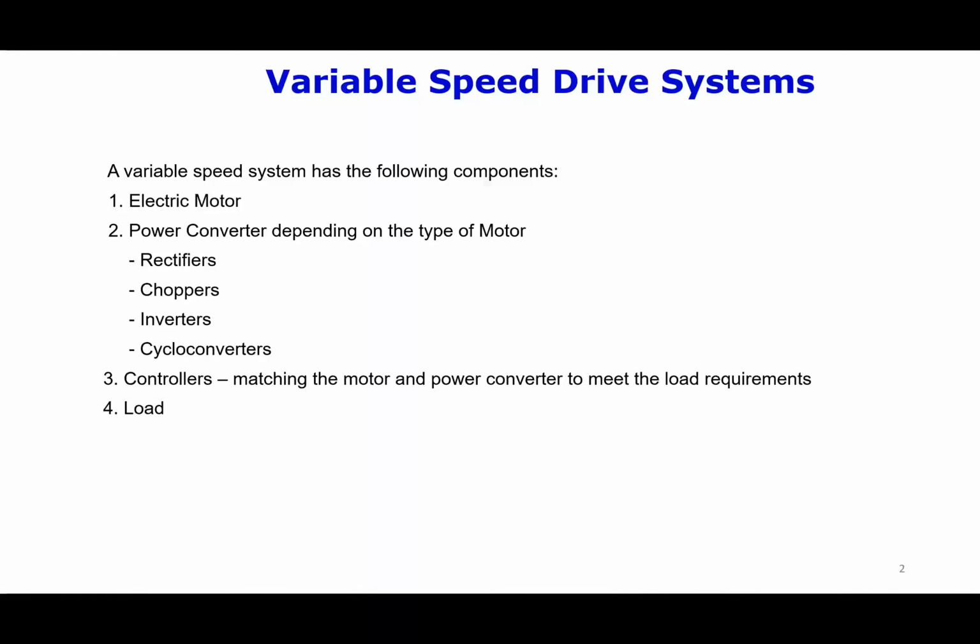Understanding of the power electronics and power converters is very important because power electronics is the enabling technology for the control of motors and to achieve the required torque and speed from the motor. The rectifiers convert AC to DC, choppers are DC to DC converters, inverters are DC to AC, and cycloconverters are AC to AC converters.